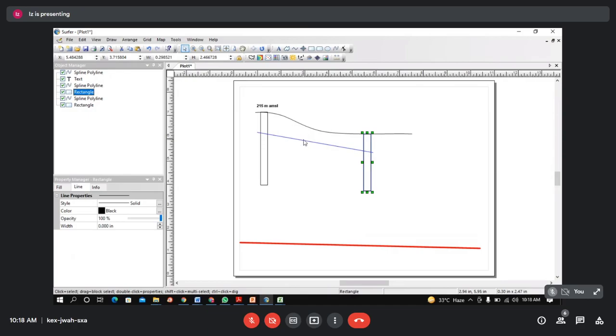So depth to water takes into account the topographic elevations or depressions, or takes into account the topography, right? While water table contour map nullifies or erases out the topographic impact, because this is constructed on a regional or a global reference, which is mean sea level. And mean sea level, as we just discussed, is the geoidal surface of sea level extending over the globe, right? अब उसमें ये जो डिप्रेशंस होंगे या एल्टीट्यूड हाइट होगी वो नलीफाई हो जाएगी, राइट?